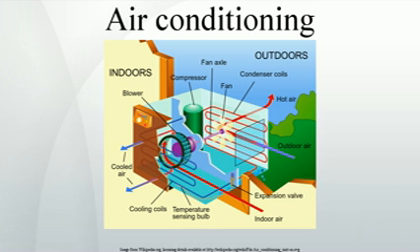It was to be phased out for use in new equipment by 2010, and is to be completely discontinued by 2020. R12 was the most common blend used in automobiles in the U.S. until 1994, when most designs changed to 134A. R11 and R12 are no longer manufactured in the U.S. for this type of application, the only source for air conditioning repair purposes being the cleaned and purified gas recovered from other air conditioner systems.